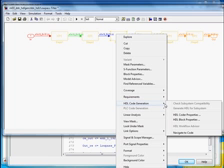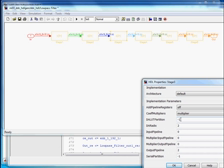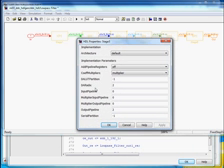some of the HDL settings here. For instance, for this block, you see a number of parameters here related to pipelining and serialization of that block. So what you have are a lot of options for controlling whether you want to do resource sharing, whether you want to insert additional pipeline stages, and so forth. These are kind of worthy of a whole webinar in their own right.